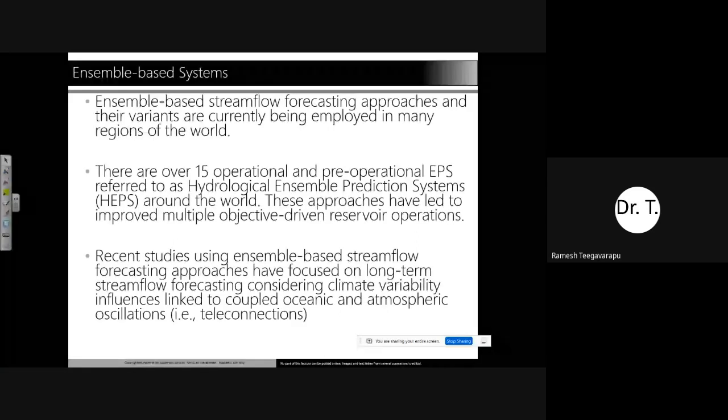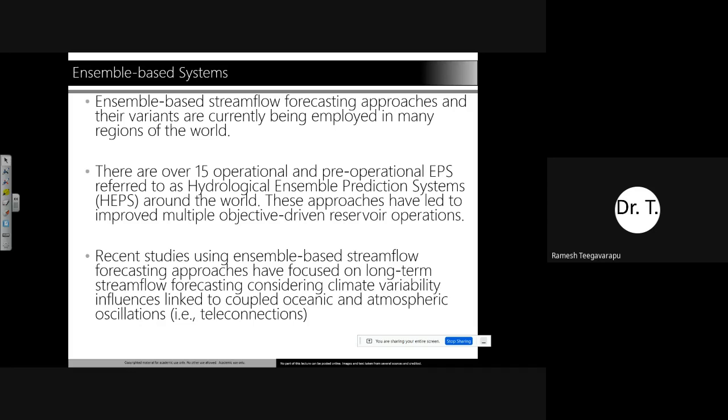These approaches have led to improved multi-objective driven reservoir operations. This is one of the take-home messages: because of these ensemble streamflow forecasting measures, the reservoir operators have a little more control on how they can handle the flood which is coming in, because now they don't have a single deterministic forecast, they have what we call probabilities associated with it.